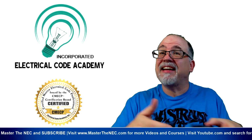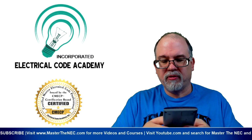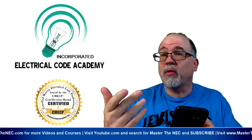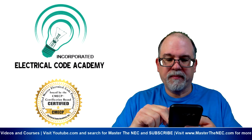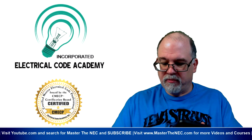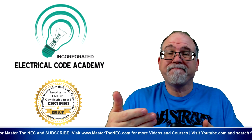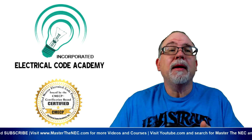We said that the secondary was 208 amperes. So let's use our calculator right here: 208 amperes times 125%, or times 1.25, whatever you want to do, equals 260 amperes. So write that down. Now, does that correspond with a standard overcurrent protective device? We have to look at 240.6(A) to determine that. I'm going to tell you it doesn't, but we need to go look at it.